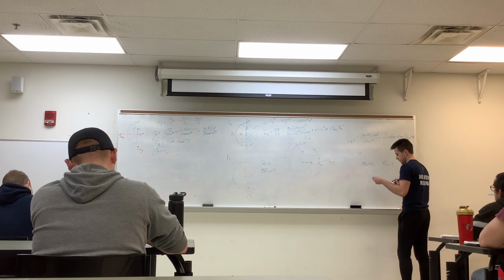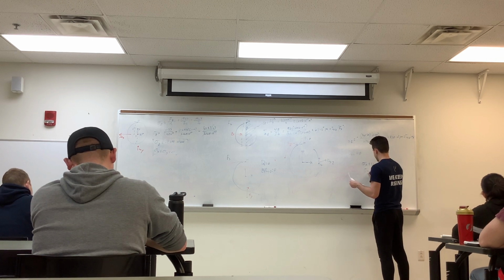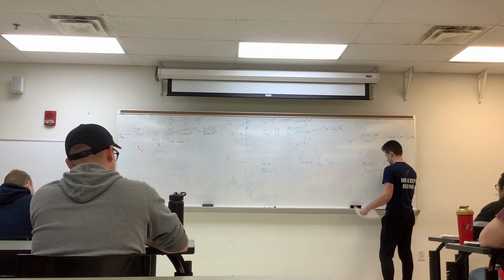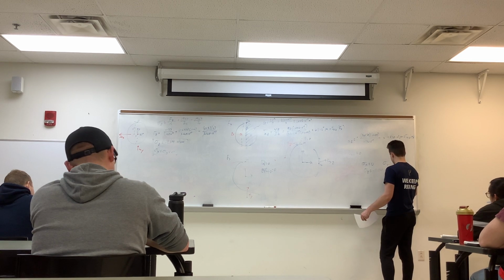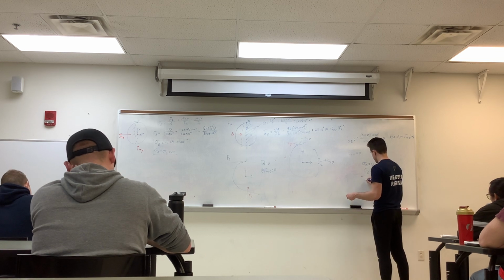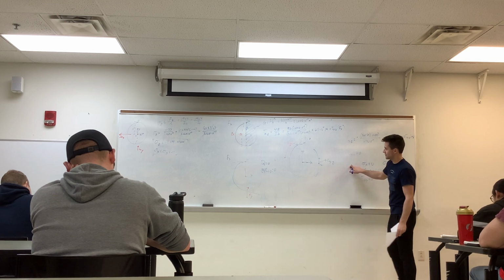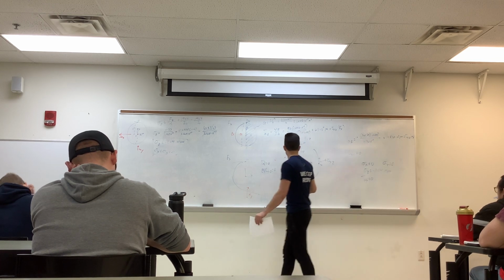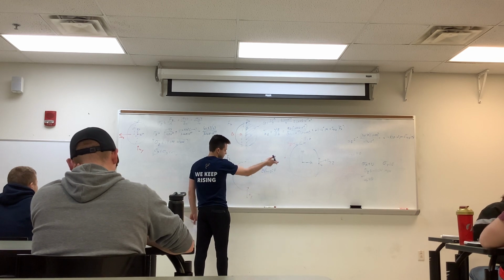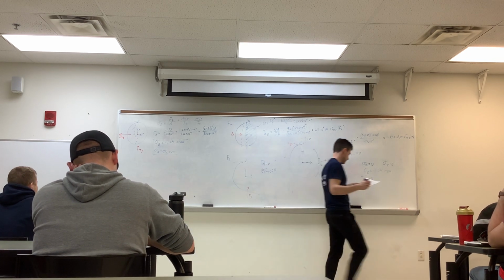We have sigma z equal to negative 1.04 MPa. We have tau xy equal to 0. Tau yz, the only one that causes any kind of shearing force in the y direction is the force in the y. The torsion doesn't, so it is equal to 0 here too.